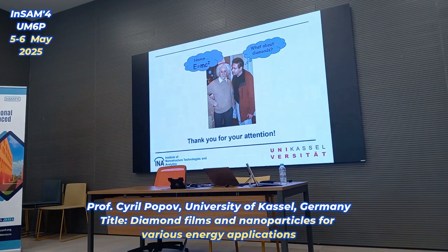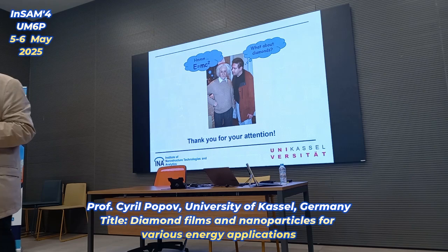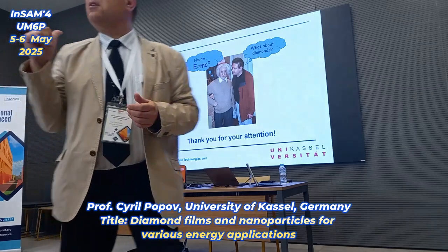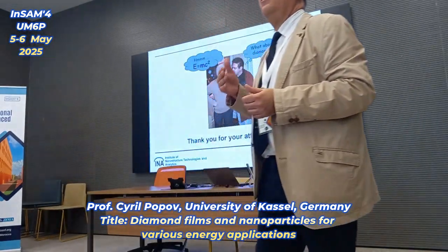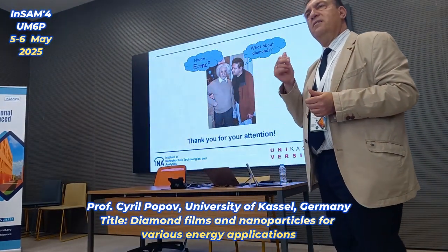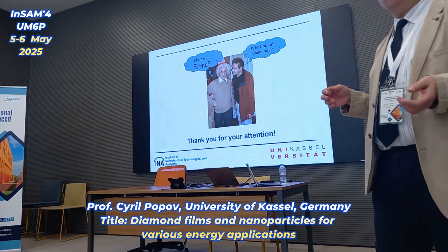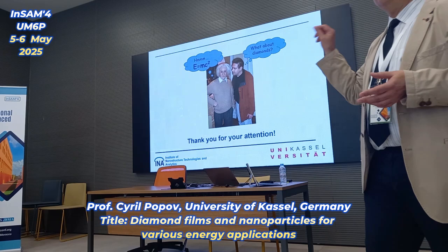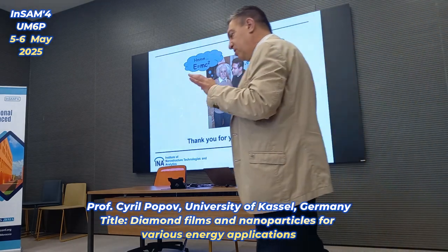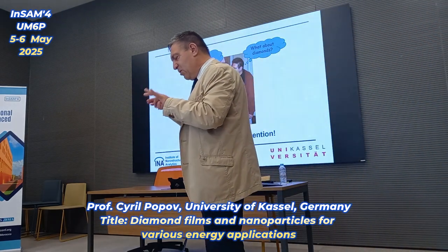Titanium, for example, is a very good substrate, but not steel. So it is not the crystallinity that is important, but the surface or the material of the substrate. This is important. Otherwise, they have good adhesion properties on substrates like silicon and titanium. We have coated implants for biomedical applications with titanium. So the adhesion of UNCD is good, although not each crystal has contact with the surface.